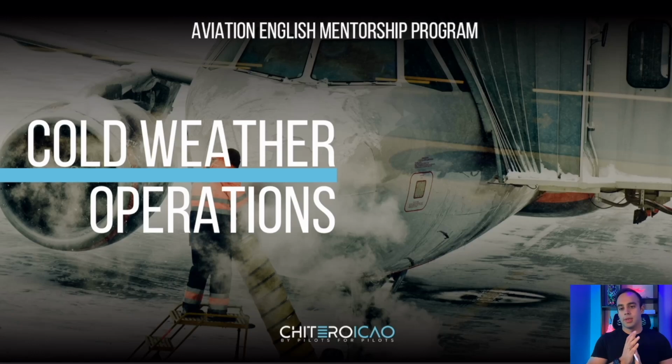Everything changes because the weather will change the air density, which will change our temperature, the temperature will change the air density, which will change our fluids, which can freeze some areas of our aircraft. And of course, even when it's a bit warm on the surface, it's going to be colder when we fly at flight level 300 or above. So we have some systems in the aircraft to prevent ice accumulation, ice accretion. And we also have some procedures we perform in order to prevent ice from attaching to our surfaces.